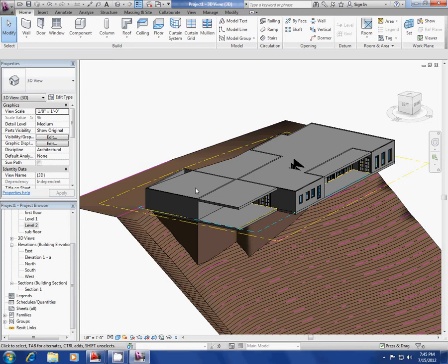Although when you copy, say I copied my floor slab from level 1 and just copied it up to level 2 in section, although things are not supposed to come with it, because it is a parametric modeling program, you may carry other components with it. And so you always want to start out with a fresh slab, a fresh floor, a fresh roof. And so in that case, I went to an editing mode and just copied just the line work. Perfect.